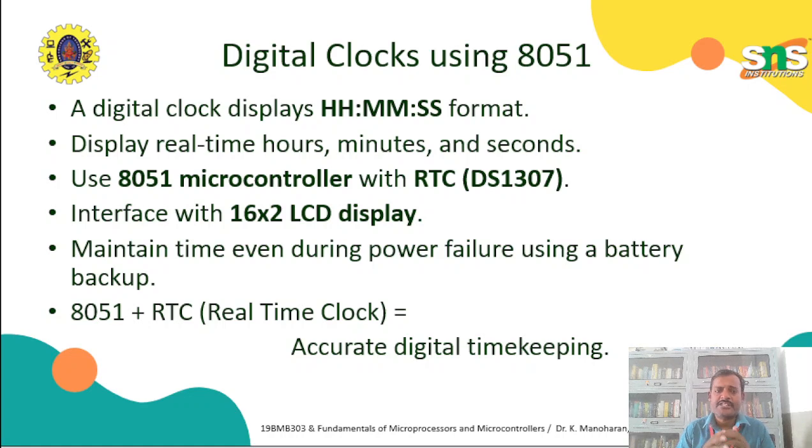For interfacing it, we need an RTC interface, that is, a real-time clock interface. We can get direct information, that is the hour, time, date, and all other information from the RTC itself. So by using this, we can simply display the information. If we need some delay units, or for example some alarms, we can have those alarms using the RTC also. For a digital clock, we need to display the information in real time as hours, minutes and seconds. So we need to use this DS1307.